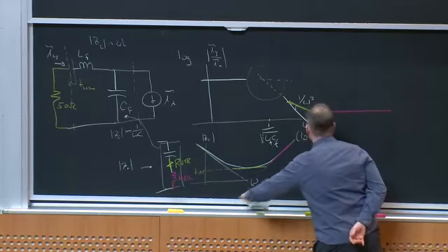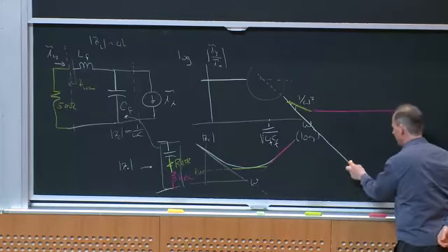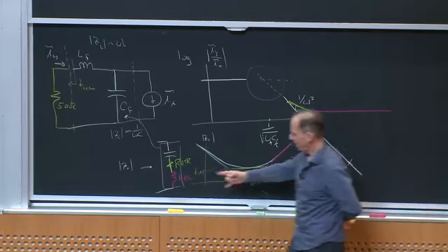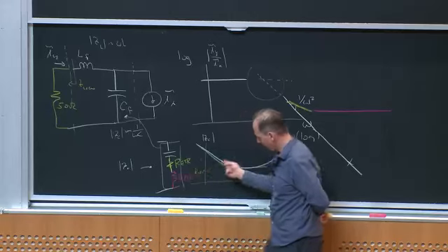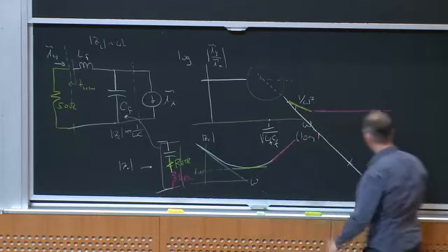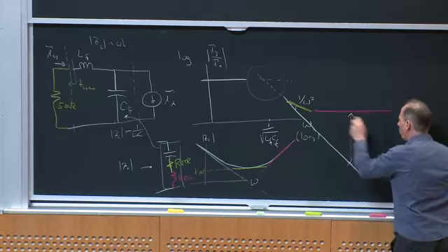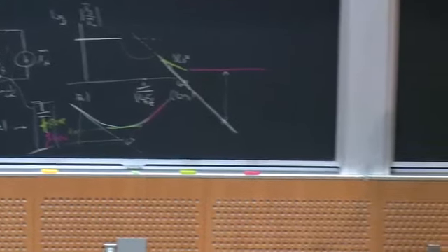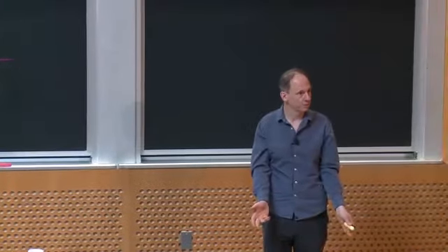So if I design my filter thinking, oh, geez, that's how I get my 6 orders of magnitude, and I come back and I'm really dealing with something where at that frequency, this capacitor doesn't look like a capacitor, it looks like a little inductor, my EMI might be way higher than I thought it was going to be. Okay, my filtering is just going to get clobbered by the parasitic inductance of my capacitor.